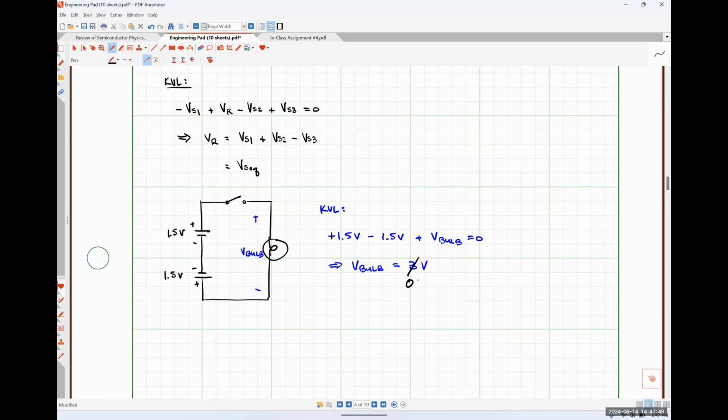You're not paying attention, you're putting the batteries in, accidentally get one of them backwards, and whatever you're trying to make work doesn't work. It's because the device is no longer receiving the correct amount of voltage. In a simple case like this, where it's exactly 2 batteries, it cancels out completely. But you guys used a battery pack in your Engineering 120 series, where you had 6 AA batteries in series, so a total of 9 volts. If you put one in backwards, you were only going to get effectively 6 volts out of the battery pack, which might not be enough to actually power your Arduino.